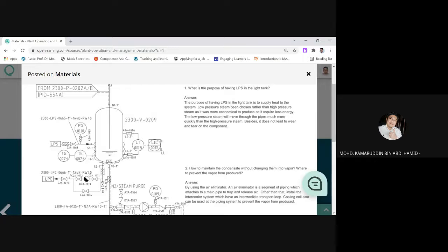You need to remember that having several buffer tanks, we call it buffer vessel or buffer tanks, in terms of operations, there are pro and also con for this. The pro for this is basically, since you have a holding tank, you may have several values of residence time. Then you may have some lag or delay time for you to do whatever after this.